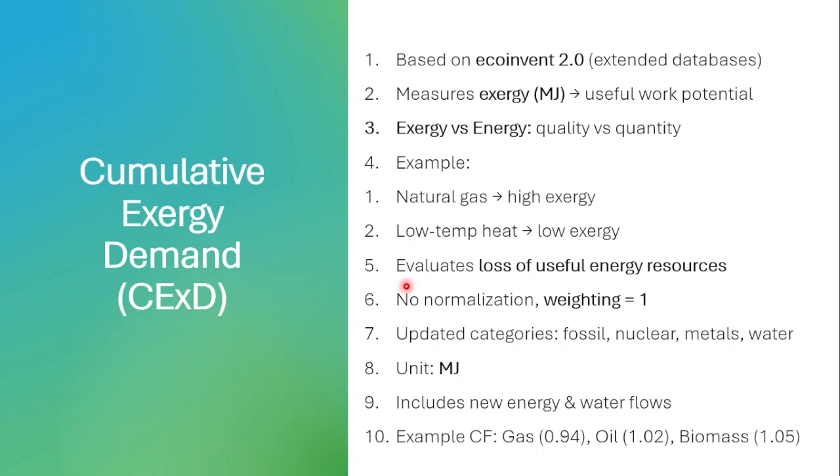You can do the exergy analysis for every system, and you can calculate the exergy efficiency based on the quality of the exergy. Also, for every component or every subsystem, you can calculate the exergy destruction rate, with the abbreviation EDR.